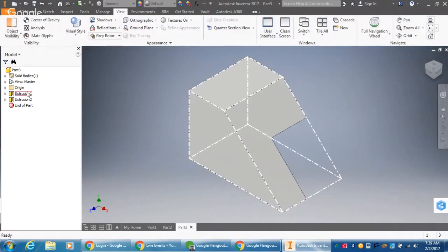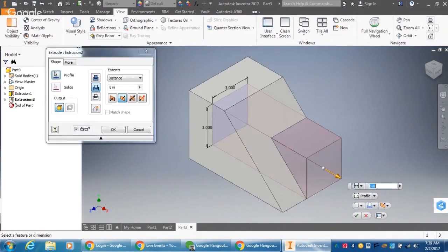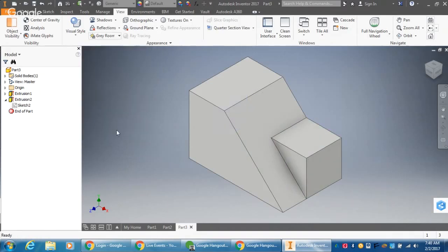Okay. So if I just double click on that extrusion, you can see cut is selected, right? Oh, we don't want to cut. We actually still want to add material, but going in that direction. Click OK. Ta-da! Magic, right? Pretty cool. So that, again, I think was another pretty simple one. We're going to do one that's going to look a little bit more complex here.